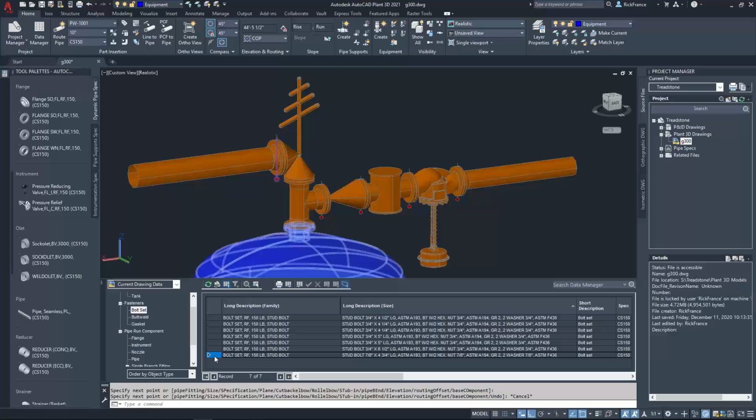So what it did was default to the one out of the box. Everything's being calculated off 4 1/4. I haven't changed any bolt lengths, so they're all being calculated off 4 1/4. It's all in the rounding. It's what those bolt standards are doing. So I'm getting different lengths based on the rounding. Since I didn't have 7/8 inch in the bolt standard to round up to anything, it just defaulted to the one out of the box, 4 3/4, the nearest 1/4 inch.